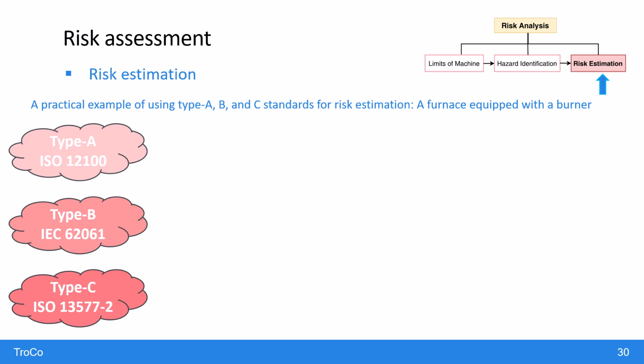When designing machinery, compliance with safety regulations is essential. The new EU machinery regulation, which replaces the Machinery Directive, requires that machinery be designed and built in accordance with all applicable EU legislation, such as the Pressure Equipment Directive, PED, and the ATEX Directive for equipment used in explosive atmospheres, as well as relevant harmonized standards like IEC 62061 and others. By harmonized standards, we mean standards recognized by the European Committee for Standardization, CEN. Following these standards supports both regulatory compliance and safety by design.